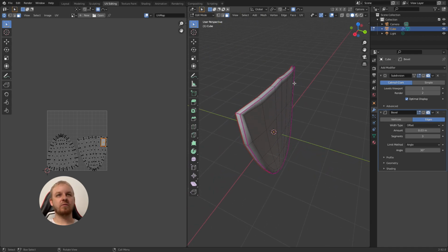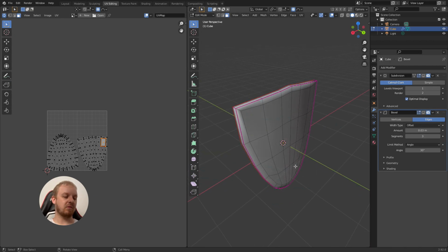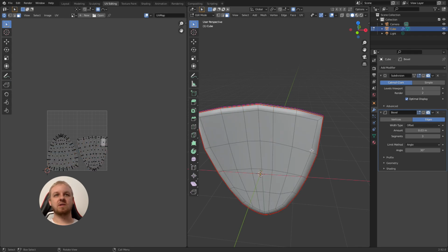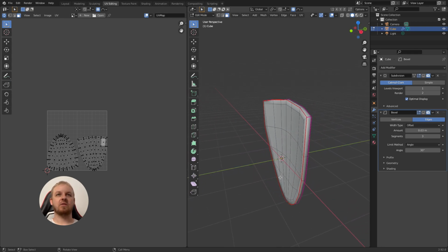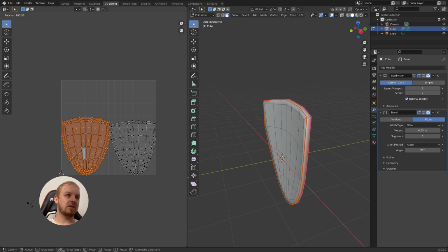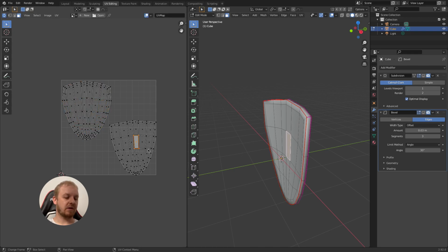So I make the front with those edges, so my design will go to those edges, and because we want to focus on the front and the back is not that important, you always want to place your seams in places that are less visible or not visible at all. Okay, what we can do now is select this and press L to select linked. Okay, escape or right click and press O if you have this influence selected. And I will just make it similar to the UV layout I had in the demo.